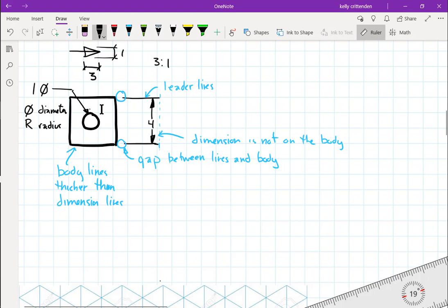How close to 4 do you need this dimension over here? You need to have some tolerances on these numbers if they're going to be something that's sent to somebody to actually make, because once you tell them it is exactly 4, it gets into a ridiculously expensive process versus, oh, well, it can be 4, but it can be 4.05 or 3.95, and that's totally fine too, and that's a completely different operation. So that doesn't matter on drawing your free body diagrams.